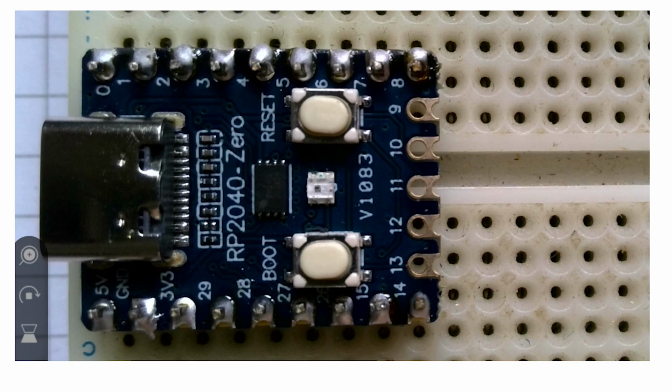If you use an Arduino Uno or an Arduino Nano, it's fine, it'll get them to work. But it's only got 32K of memory. And if you start putting more and more and more NeoPixels on, then you run out of that 32K pretty quickly, because you're going to need a big sequence. If you've only got one or two NeoPixels, then you've only got half a dozen or a dozen possible states.